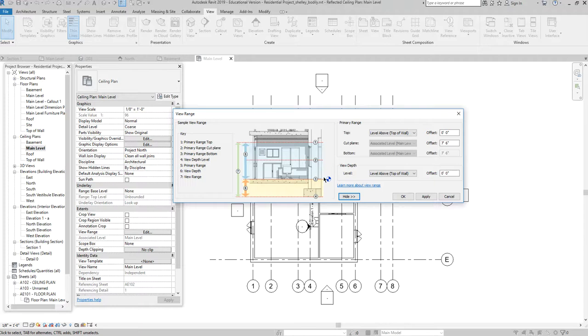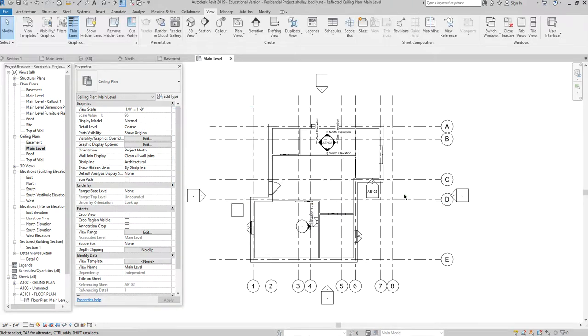With a ceiling plan, it's opposite, all right? We look from our floor plate up with a ceiling plan, and our cut is at 7'6". Okay, so we're looking probably somewhere in the range of, maybe even above that window, right? In this range, up. Okay, so that's how a reflected ceiling plan works. Instead of looking from your cut down, like a floor plan, you look from your cut up. And instead of the cut being from 4 foot looking down, it is from 7'6" looking up. Okay.